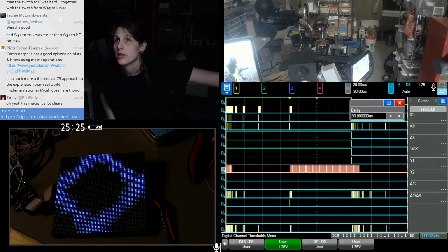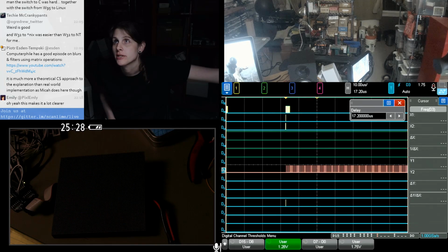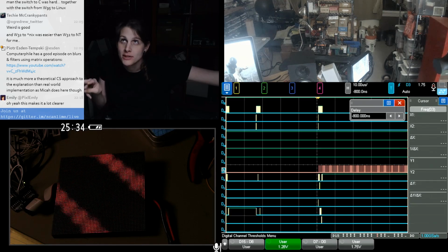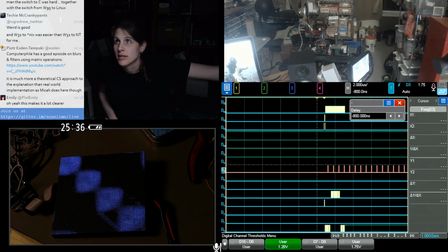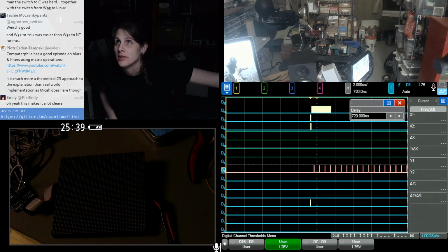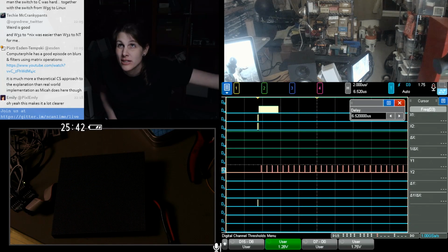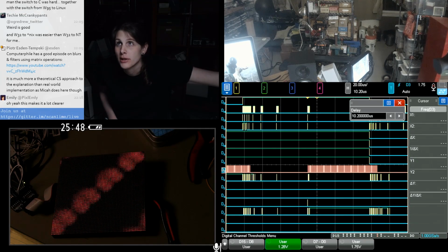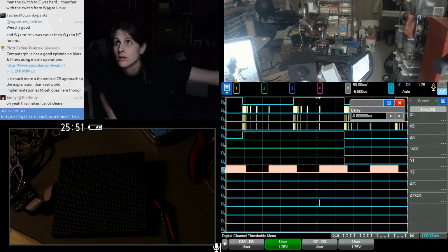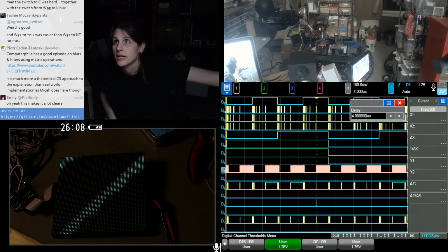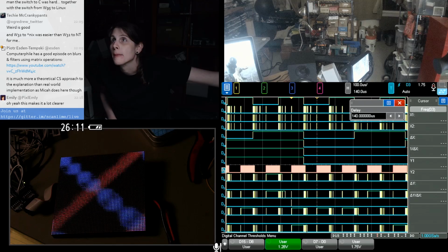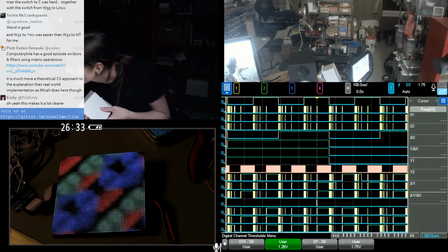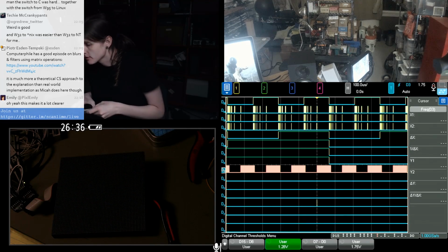The shift register at the bottom that you see shimmering on D0 through D6 is handling 64 pixels at a time. But it does that for 2 pixels in parallel, whereas the renderer processes 1 pixel at a time. So the pulses on D7, if you counted them, you'd see 128 of those, I think. But they happen once per row, whereas on the bottom, those happen once per modulation cycle. And then that pulse on D3 is the beginning of the frame. It's a pretty nice pattern. It's not quite symmetric for the reasons I mentioned, but it looks good.